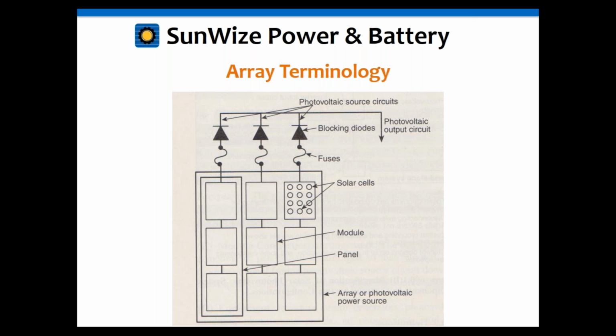I'm not going to really talk about blocking diodes too much because they're really not used anymore. Blocking diodes are kind of an old thing. Those have mostly been integrated into the charge controller, so you don't really need to worry about them much anymore. But what isn't shown here, we will talk about, is bypass diodes. Those are important, especially for troubleshooting, so we'll touch on those in just a minute.